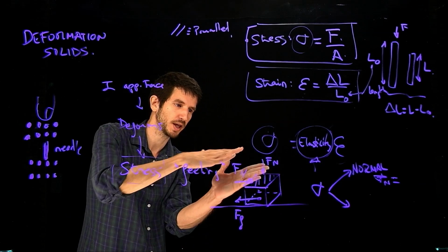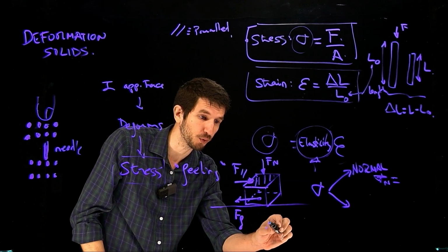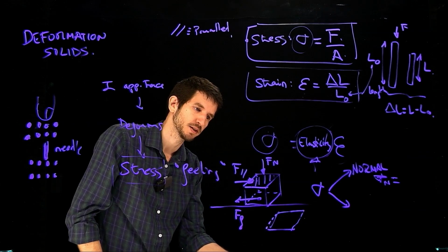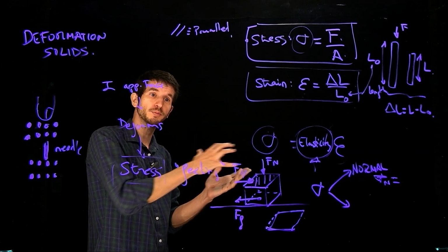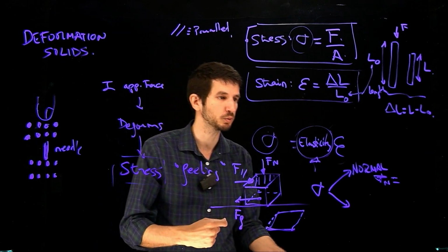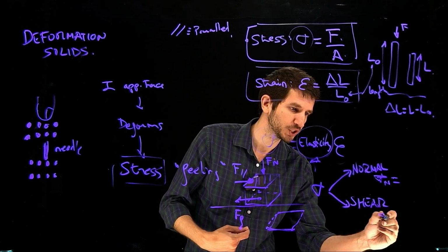So what happens when you push gelatin sideways? The thing is going to deform. So it's just going to end up as a block of gelatin like this, right? And that sort of stress is also going to deform the object, therefore there's going to be a strain, but now that sort of stress is what we call shear stress. And that is responsible for shape.